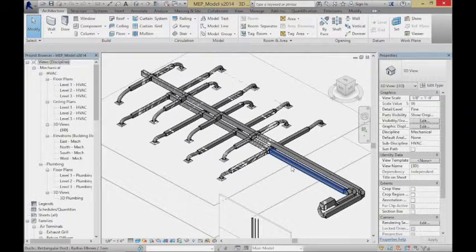If I have to accommodate an awful lot of those bends, we'll have to have a bigger duct system to push all the air, to overcome all the inefficiency that we're introducing through all the different bends. So we like to keep things as straight and linear as possible, with the fewest number of bends and elbows. That works okay until you start playing around with the notion of the amount of space between the floor above and the ceiling below, where maybe I even have some structural work in here.